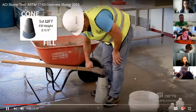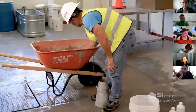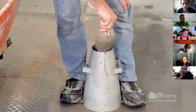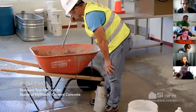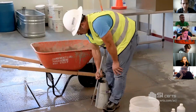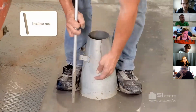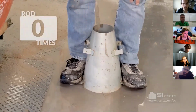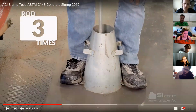Let's continue. First layer: pour concrete around the mouth of the cone to evenly distribute. We'll rod this lift throughout its depth without forcibly striking the bottom. Half of my rodding is going to be at an angle to ensure that I get proper penetration into the corners. The rest will be across the cross section. What is the reason he's rodding the first layer? He's trying to avoid something. Bubbles? Exactly. Perfect.